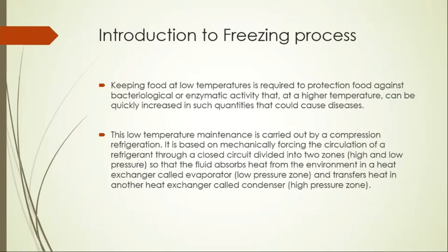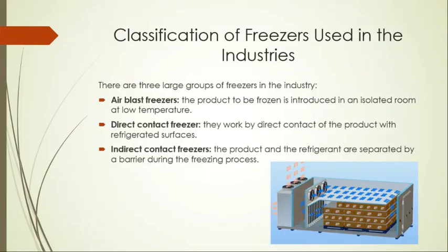Vacuum absorption chiller is widely used where you need to cool down your stream or product, or maybe the raw material, within a range of 0 to 4 degrees centigrade. For that it is quite suitable, but definitely it also depends upon the environment as well, like if you are utilizing it in very hot conditions like in Karachi, it might not work so efficiently in summer.